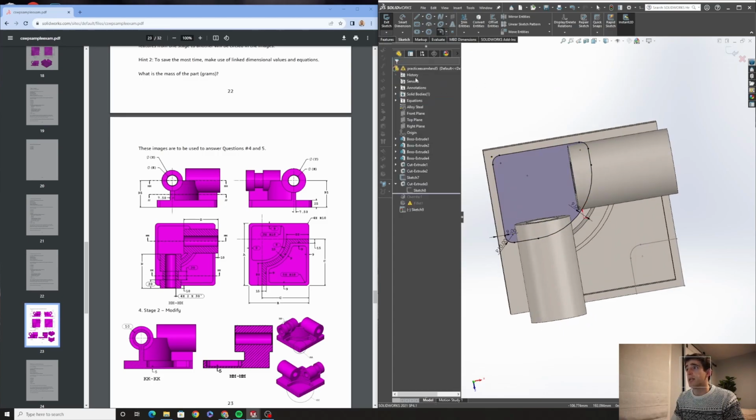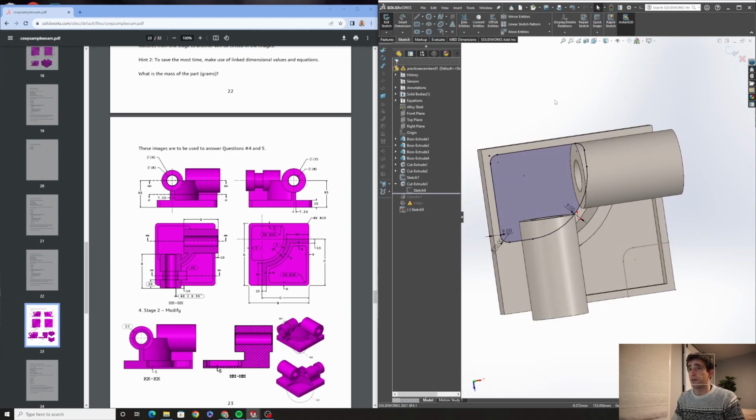It's kind of the same thing. It's just in the sketch instead of a feature. I prefer using a feature rather than the sketch fillet. This just creates a tangent arc. I think the feature is easier to edit later, but this works just as well. So let's double check HH and MM section view.